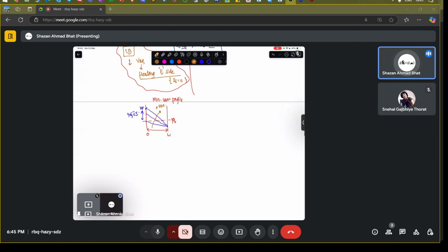But the point here is what we do, we float the E side. That means we make the VBE approximately equivalent to zero. So when VEB is zero, you have negligible injected carriers, below the background doping concentration of the base region. So this is the curve when VEB is very small.